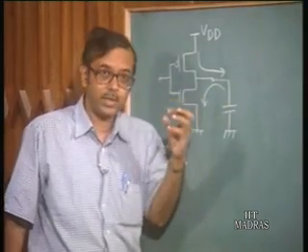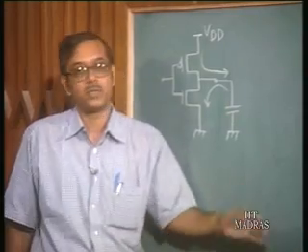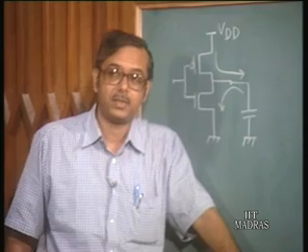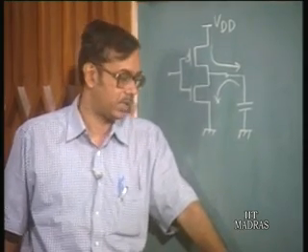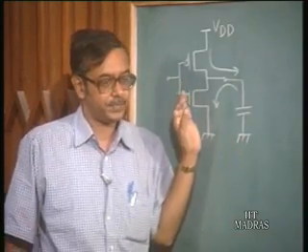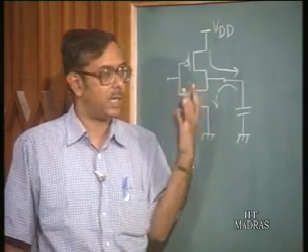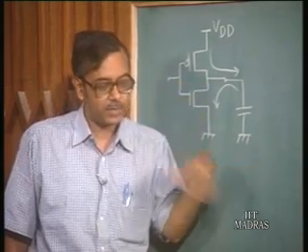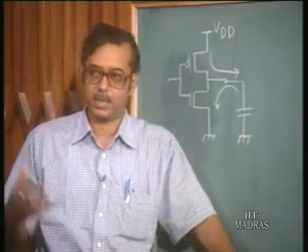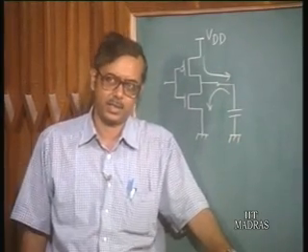So, basically the bipolar transistors have certain inherent advantages, that is the higher transconductance as well as larger current drive capabilities, which also makes them very highly suitable for high speed logic circuits. So, on the one hand we have the advantage of CMOS, that is 0 static power dissipation, and some other advantages, while on the other hand the bipolar transistors have advantages like being a high speed logic family, by being a high speed device, in the sense you have higher transconductance.